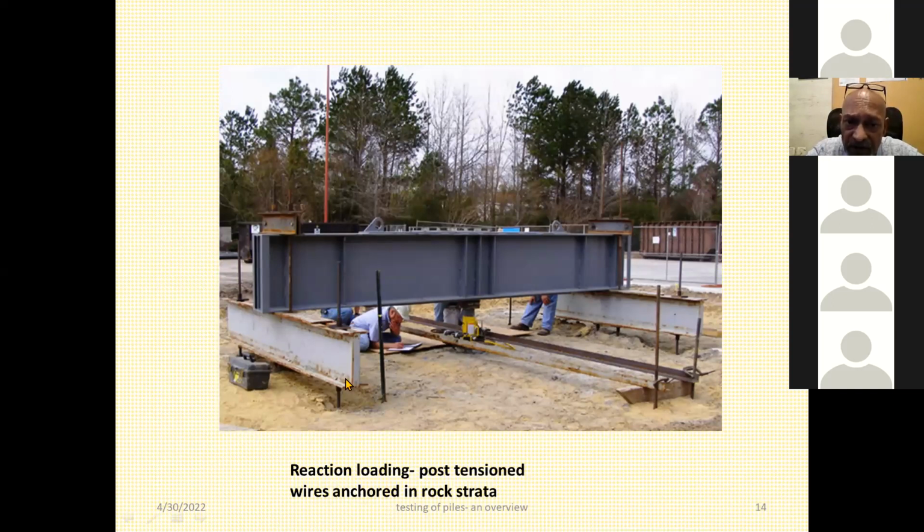They are pre-stressed wire, which are grouted in the rock strata below, and the hydraulic jack is placed against this bearing beam, and the load is applied on the pile using the reaction of the strata through this kind of arrangement. This is very common because you don't need a lot of gravity load, and this is really much simpler.